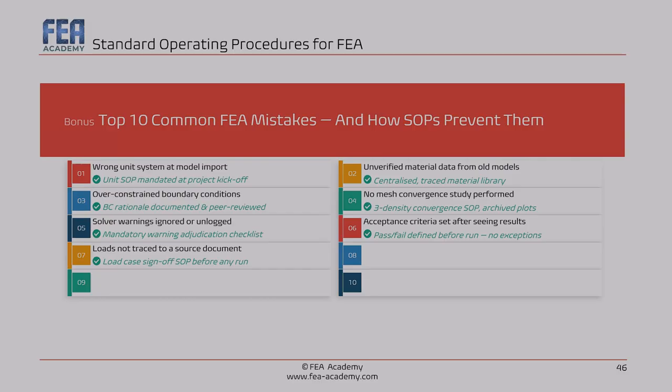Also, the loads not traced to a source document. Where did this 50 kilonewton load come from? If the analyst can't answer that question in 30 seconds, the load is unverified. The fix is a load source field on every load definition in the analysis plan. Okay, you know where the loads come from, and if you define the loads, you know the method you use in order to define them, and you document this method in the analysis plan.